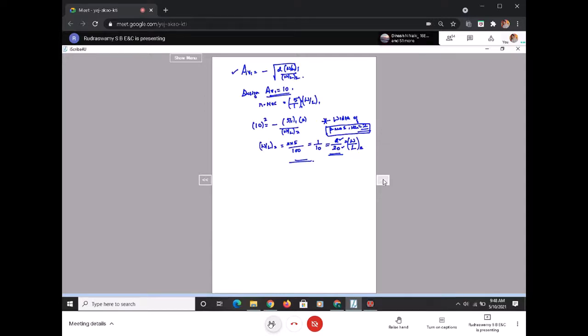This is what I think Geeta Patel asked at the end, when I had asked for any clarification. She had asked why the width and length ratio of the PMOS is the opposite. So, clarified there: since M2, that is the PMOS, is now acting as a load, instead of a passive resistor we are ensuring that this is acting as a constant current source. So that's why we are not worried about the width and the length, but only the width. The minimum this software or design requires is 2. Is that okay? Hope this is fine now.